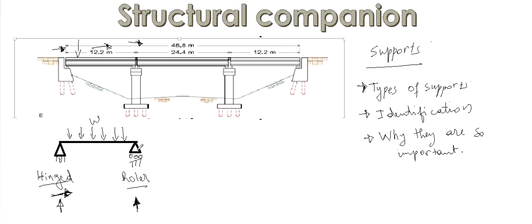There is no restraint. It can go all the way. So there is nothing that can stop the movement. If it would be in the case of a hinge support, there's no movement. That's why you have to determine the horizontal reaction.